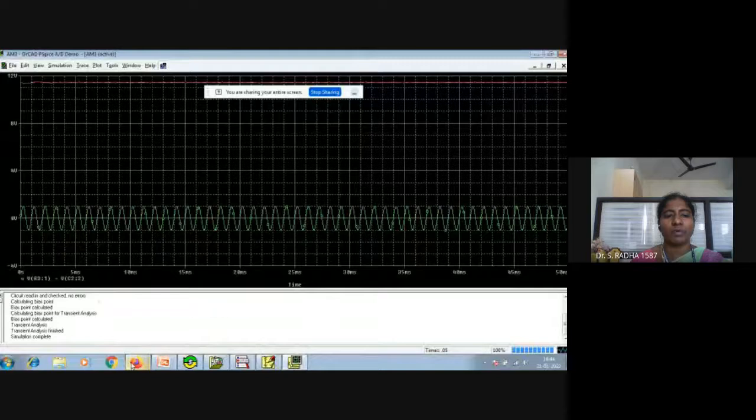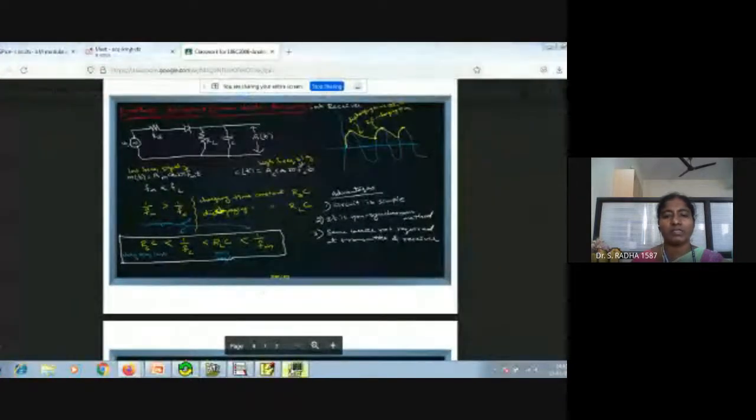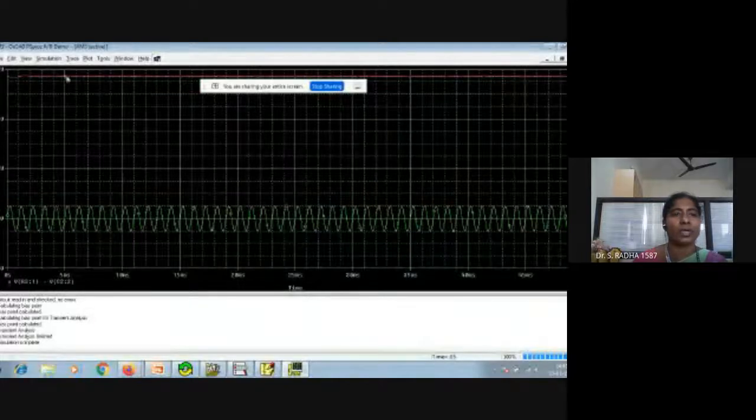Okay. So in the waveform also I showed you. You can see the blue color. It is on both sides, positive side and negative side. But the yellow color is only on one side. This is the yellow waveform. Its frequency is different, so the proper sine wave is not visible. Okay, this is the demodulated. It is only on the one side, around 11. When I show it separately, we are able to see it as a sine wave at around 11 volts.